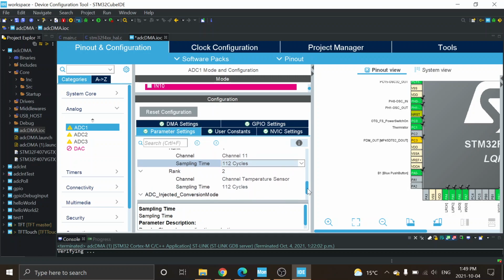So I'm just wanting to say, hey, just slow up a little bit, give it time for us to read in from the temperature sensors. If I had both on one channel and it was an interrupt, the DMA can handle it, but on the interrupt it would happen so fast that you would mostly be in the interrupt. You wouldn't give it enough time to go do other things, and all of a sudden things don't work anymore. It's doing the conversions and you're jumping into the interrupt routine, and that's all you're getting done.